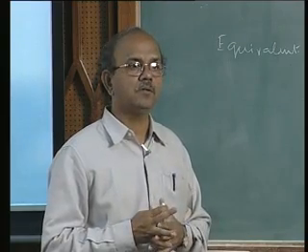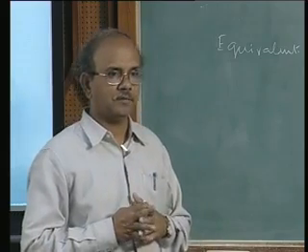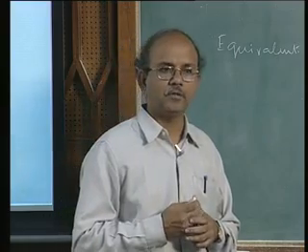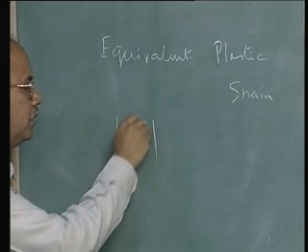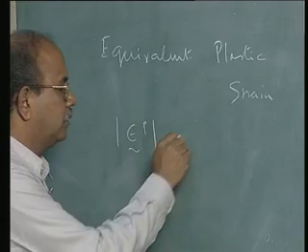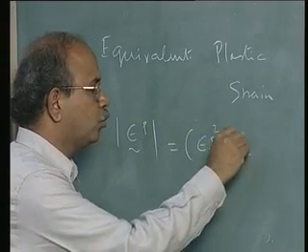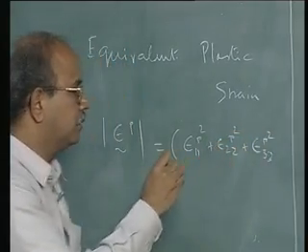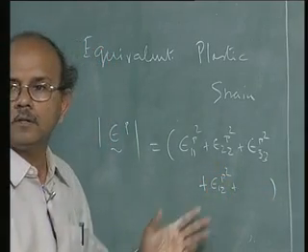Right? How do I write this down? Of course, this would depend upon the norm or length of this vector. So, that is very obvious. So, you can write down that as ε̄p rather of this vector, which would be in terms of (ε1^p squared plus ε2^p squared plus ε3^p squared plus ε12^p squared plus and so on), whole power half.